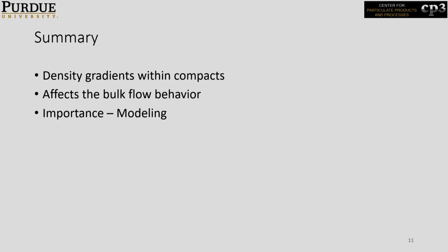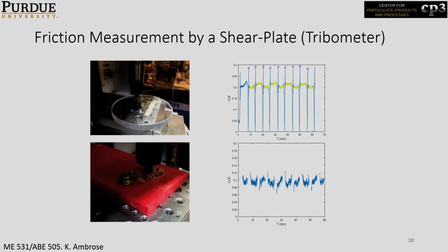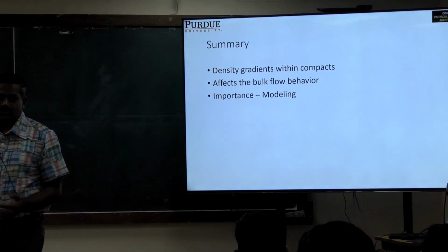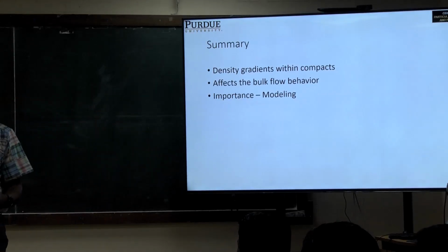If you are working on friction measurements, maybe you can check with them. It's easy to modify those in this setup. So my student, most of it, he 3D printed the surfaces and then attached them and measured those. So again, it affects conveyance and the energy needed to convey. And when it comes to modeling, it plays a big role. So you'll have to know the accurate friction values, especially when you are using discrete element method models, right?